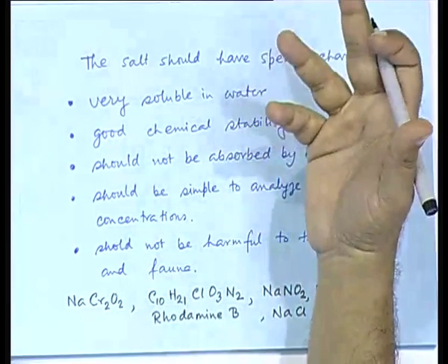Now, the flow rate varies with time, right, because of the season changes. Since the seasons change, the flow rate varies, and you have to have an estimate of how the flow rate varies with time. So, if you do this measurement periodically over a period of a year or so, then in the July-August months there is a rainy season and a high flow rate. In January, there is a very small flow rate. So, you need to have an estimate of that, by measuring at different times.